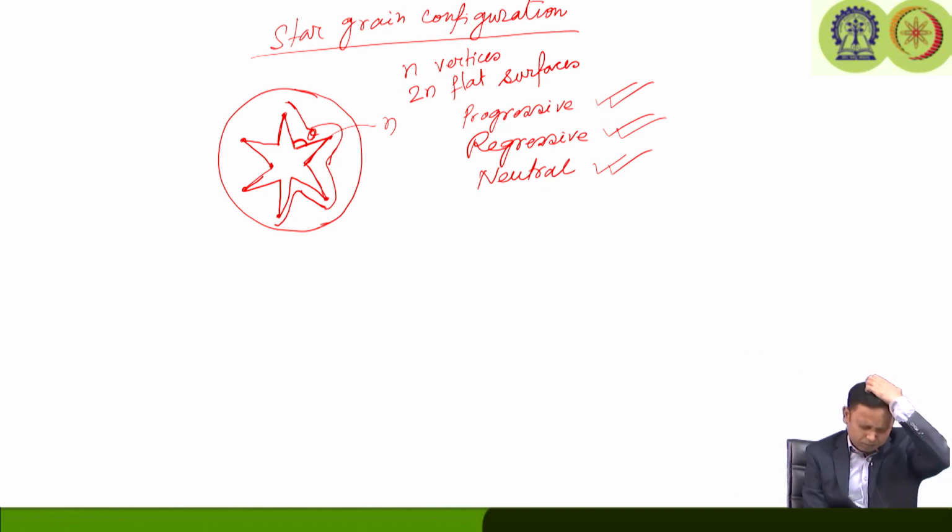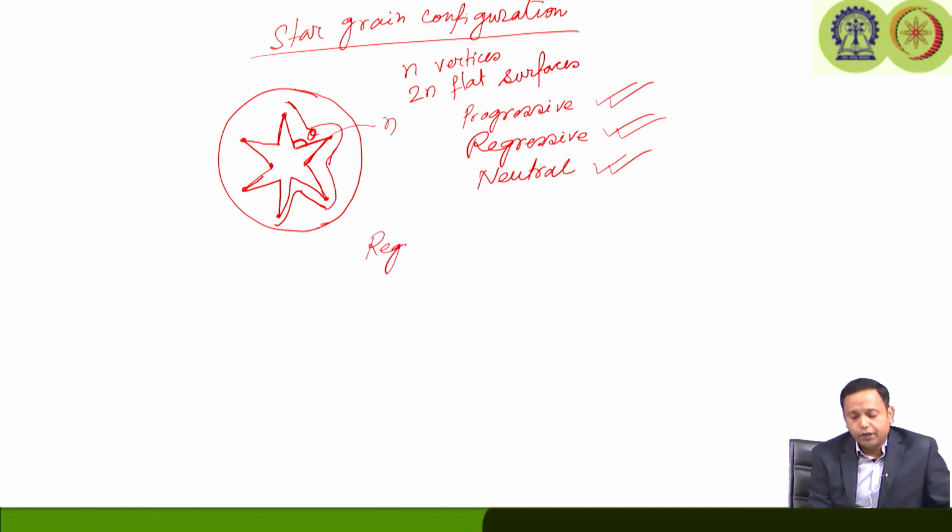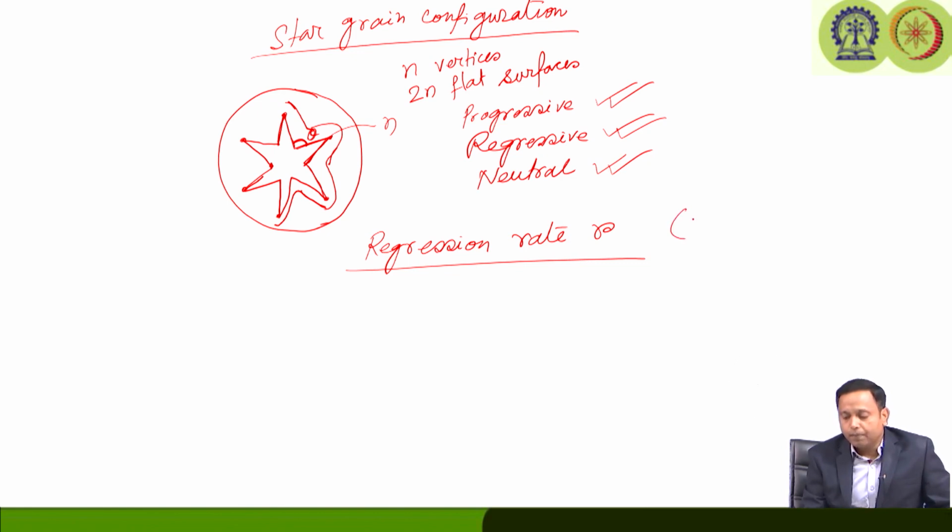All right. So, let us try to look at the various propellants used for solid rocket. But before moving into that, we talked about one thing which is called the regression rate in the previous lecture, rate r. I may forget later on, so I should at least mention here that the regression rate is the length regression over time. So, it is like millimeter per second or meter per second, but it is defined as the length regression, like if it is a radially outward burning, how much radius has regressed over time.